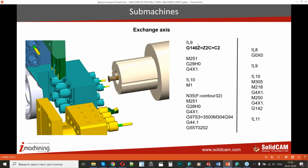So it says that from this line, I will have my Z axis on the first channel as the Z2 axis from the second channel, and I can't have a Z axis on the second channel after I added this line. And my C axis is the C2 axis from the second channel. That means that after this line, if I add any lines with Z and C, the machine will move Z2 and C2 of the subspindle.